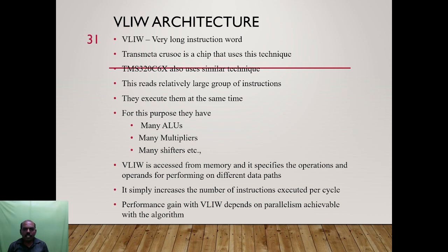For this purpose, they have many arithmetic logic units, many multipliers, many shifters, etc. A VLIW is accessed from memory and it specifies the operations and operands for performing on different data points. It simply increases the number of instructions executed per cycle. Performance gain with very long instruction word depends on the parallelism achievable with the algorithm.